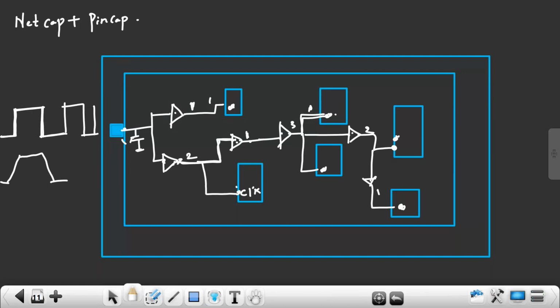Buffers. See what happens here: this clock edge, whatever I am seeing here, I will not see at this flip flop at 0 nanosecond. To this flip flop, I will get this clock edge after 1 nanosecond delay because I have the delay of a buffer here. This clock edge will reach this flip flop after 1 nanosecond. The same clock edge may reach this flip flop after 3 nanoseconds because in between I have how many buffers? 1, 2, 3, 4 buffers.